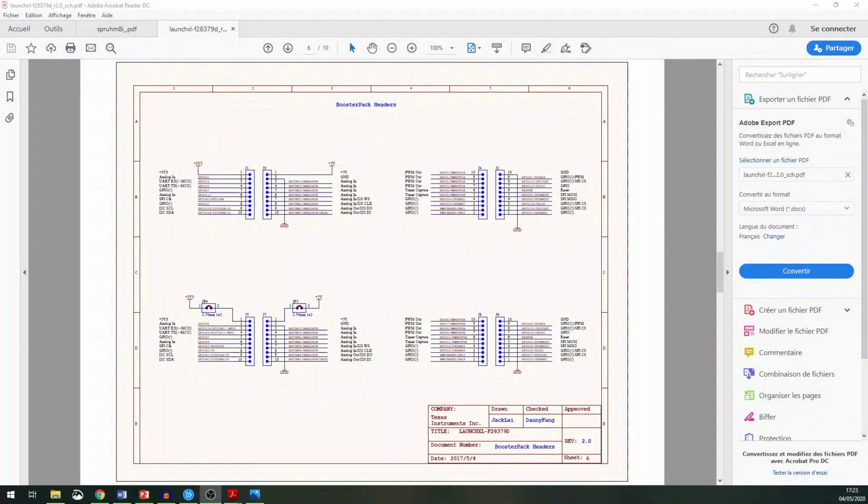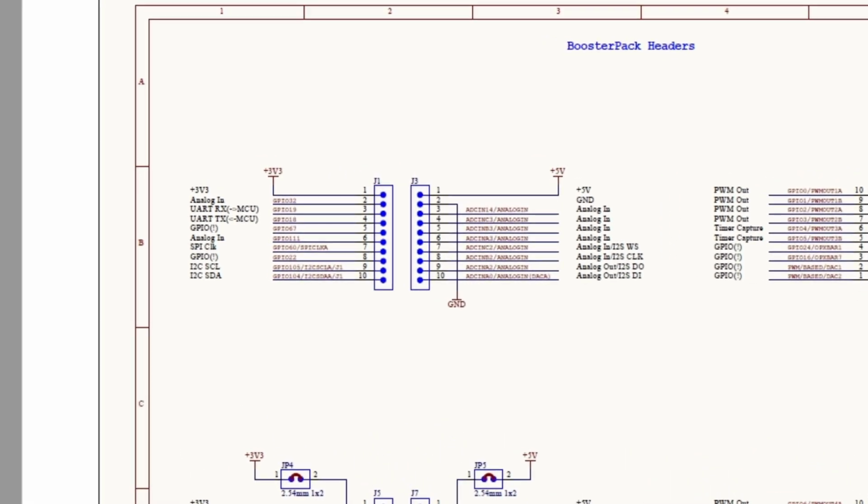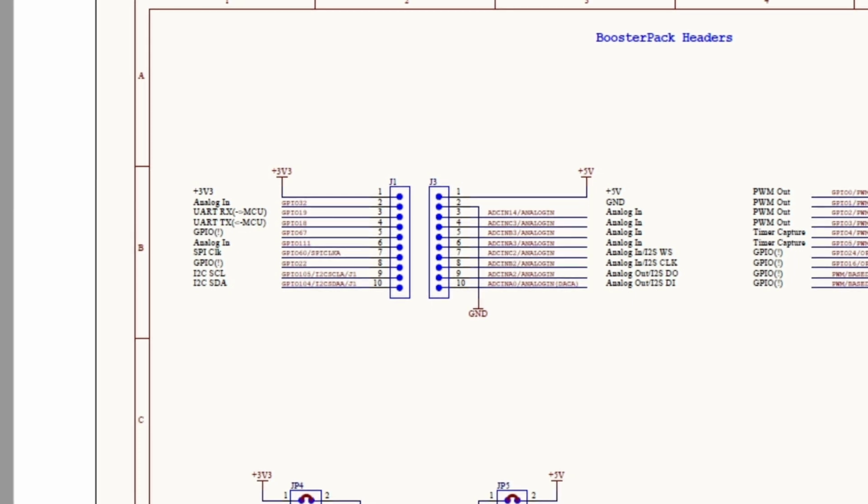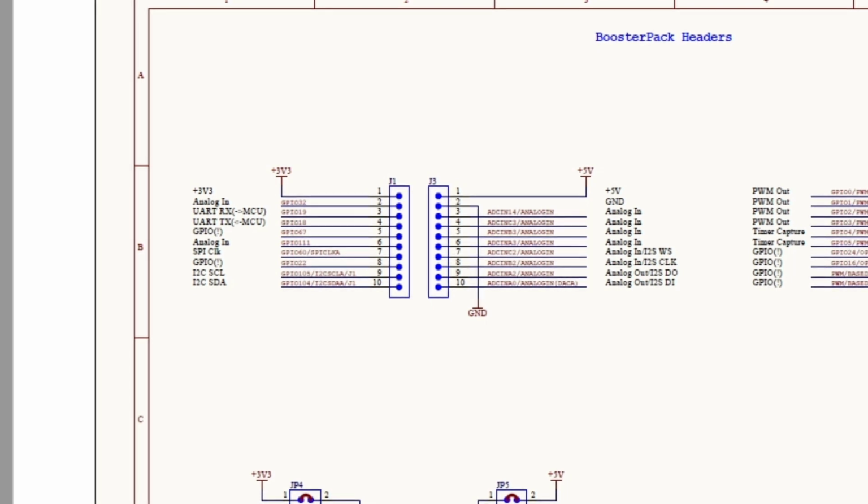Each ADC could convert 16 SOCs, and each SOC has its result register, and each result register could be related to any analog input. ADCA and ADCB will convert an input voltage: ADCA channel A0 and ADCB channel B2 will be fed by a voltage from the same potentiometer output.